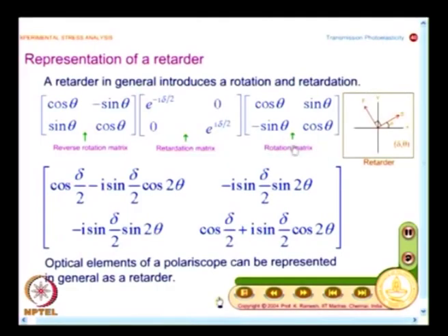of the specimen. So, the thinner the model, the better, but if we have a thin model, when I apply compression it will buckle. So, you need to have thickness so that buckling is avoided. So, these are all practical considerations. So, you have to understand the practical considerations and also appreciate the approximations involved. And what we have seen in a retarder is, a retarder introduces a rotation, and within the retarder you are adding or subtracting retardation only along the fast and slow axis, that is only along the principal stress direction. Remember this.